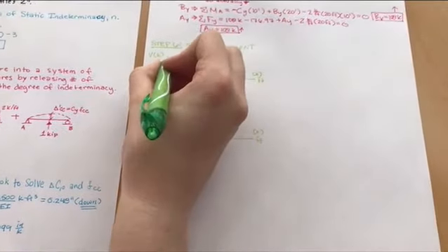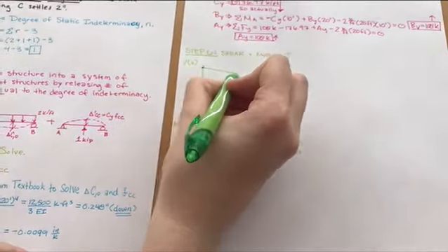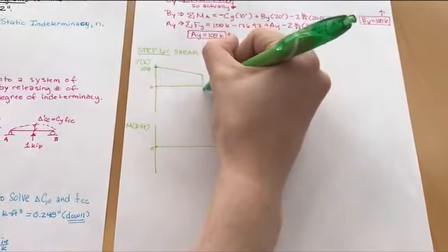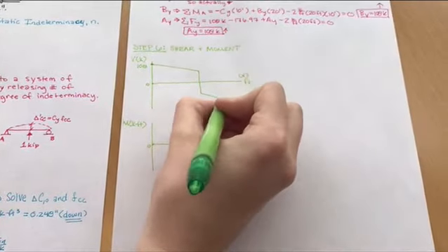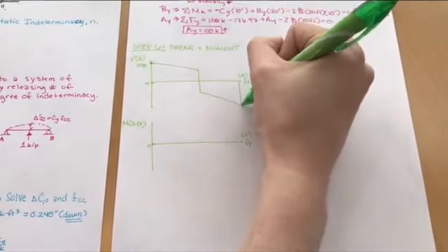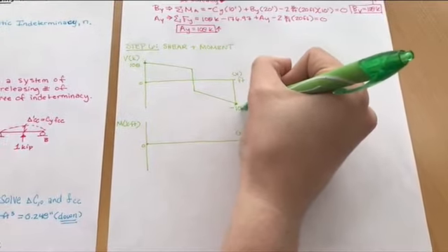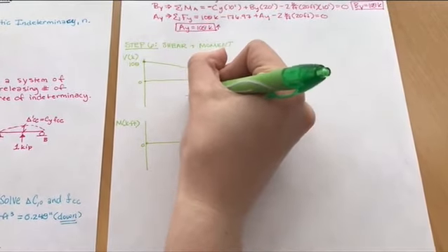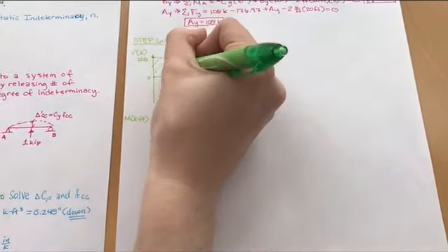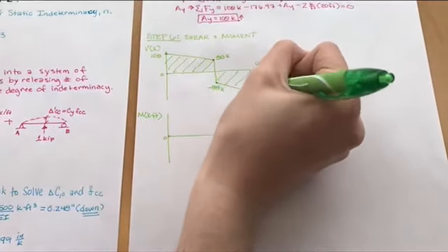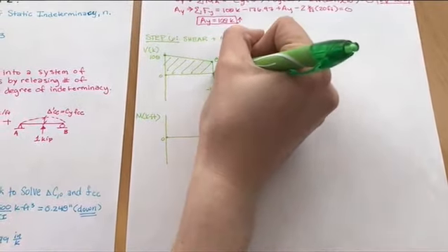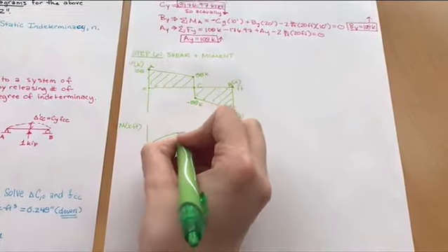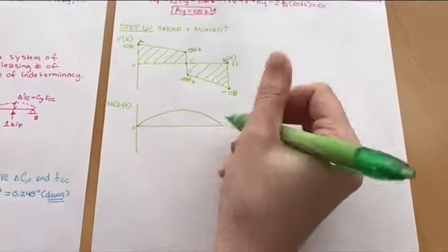Now we can finally draw our shear and moment diagrams by plotting the initial starting point and knowing we have a downward distributed load which reduces in a sloped linear line all the way down to 108 negative after you jump down from the reaction at CY. Now that those two lines slope down, you will get a parabolic function for the moment.